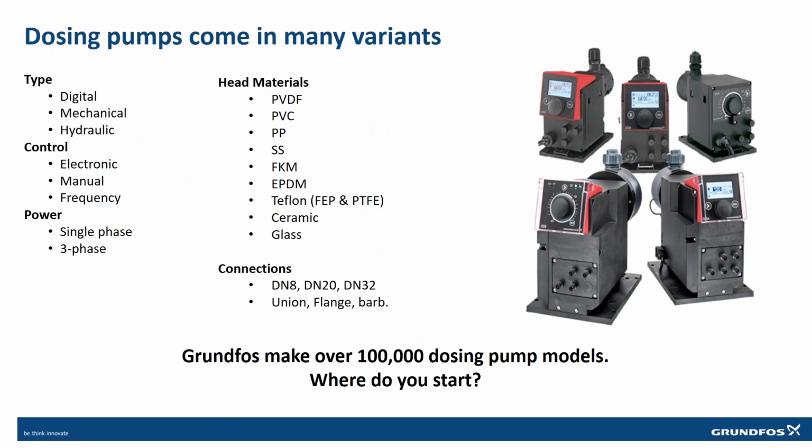From a Grundfos perspective, dosing pumps come in many variants, different shapes and forms. There are different types. Digital pumps, where you get a display that shows you what's going on. Mechanical pumps, where you only have the mechanical stroke adjustment. Hydraulic pumps for high performance, long life, etc. Different control methods. Electronic control, where everything is controlled internally. Manual control, where you adjust the stroke length or movement of the diaphragm. Frequency control, where you have a VSD and change the motor speed to change the output of the pump. Of course, there are a couple of different power requirements, single phase, three phase AC power. We need to know what's available there.